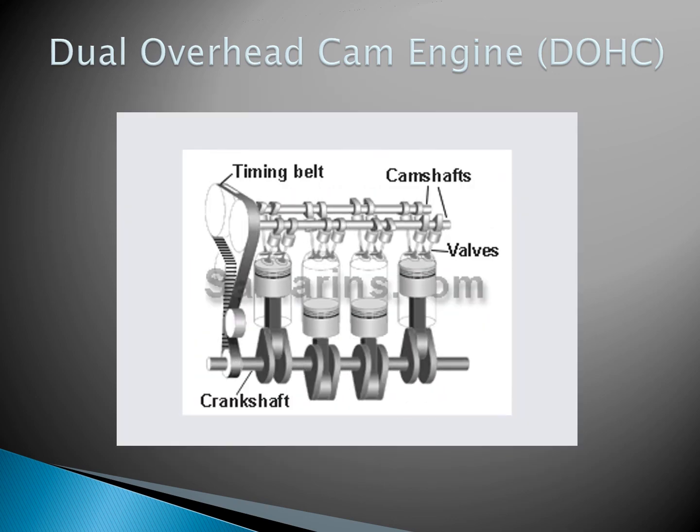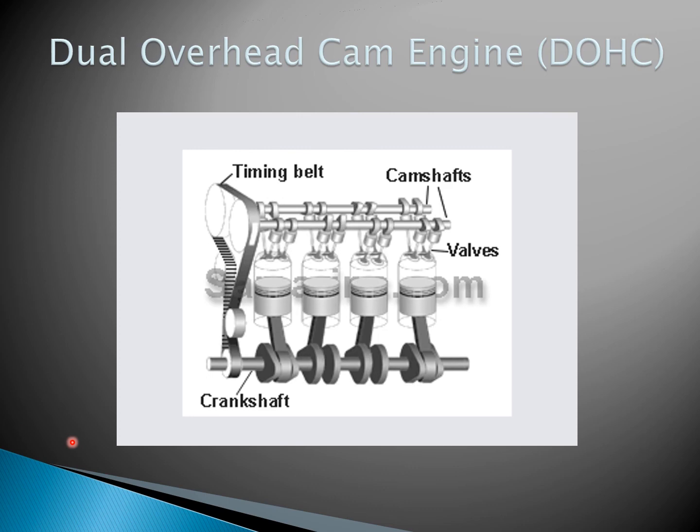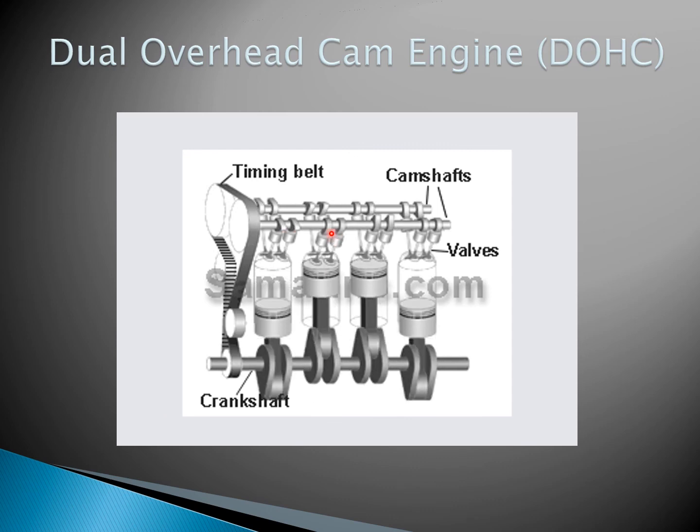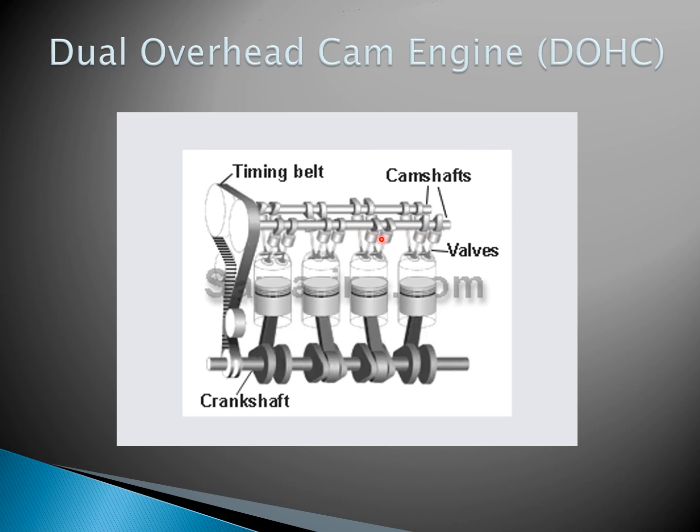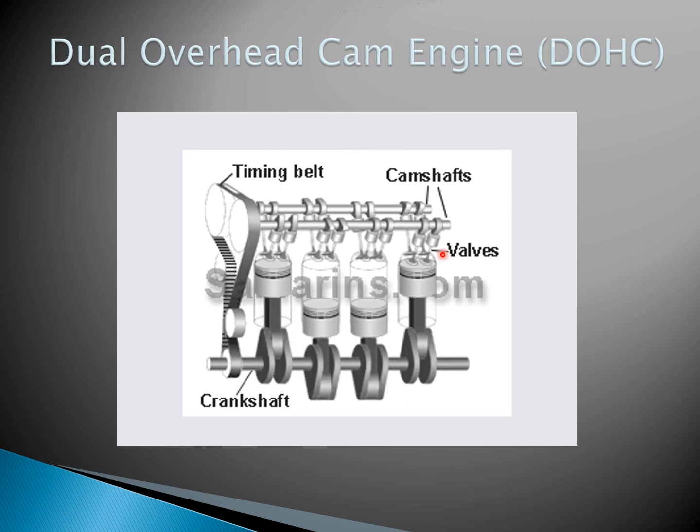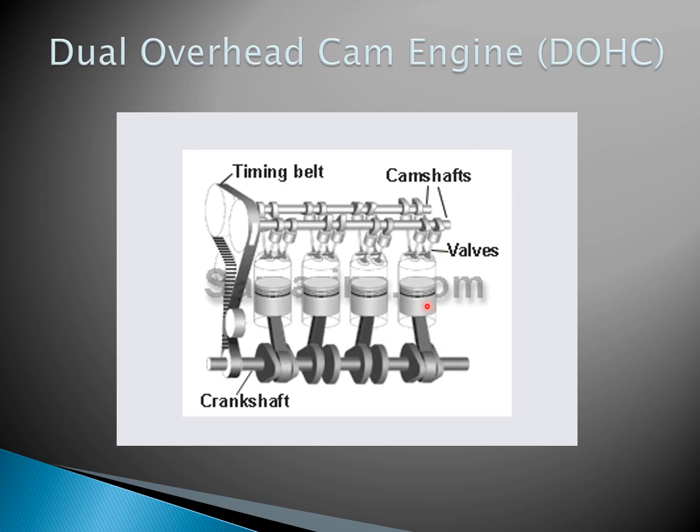All right, so this is actually the last slide in this 22-minute long video that I've had so far. Can't believe that. But here you've got a dual overhead cam engine in motion. You'll notice that since I have an intake camshaft and an exhaust camshaft, let's say this side is our intake, for each piston the intake valves open at the same time. If you have 2 valves for each cylinder, that'd just be intake and exhaust. If you had 4, you would have 2 intake and 2 exhaust, allowing more fuel-air mixture to get in so we can have a bigger bang.